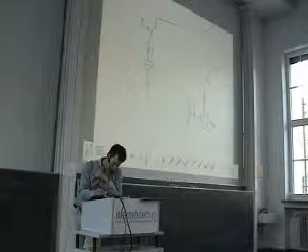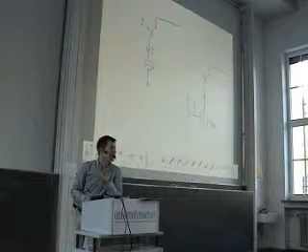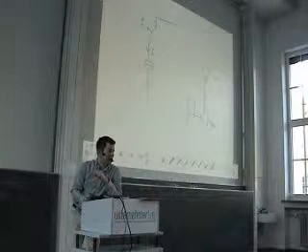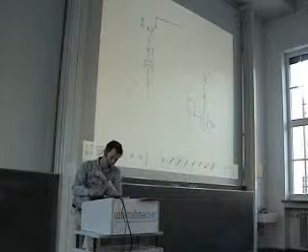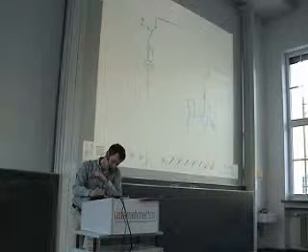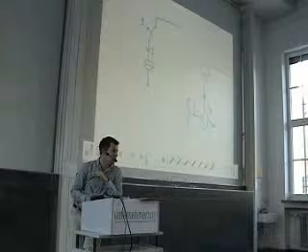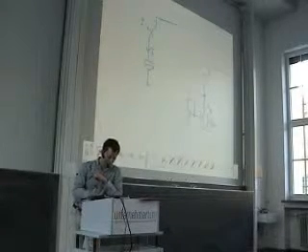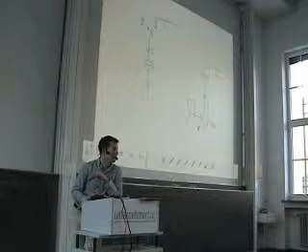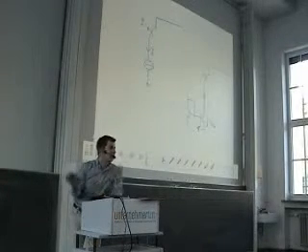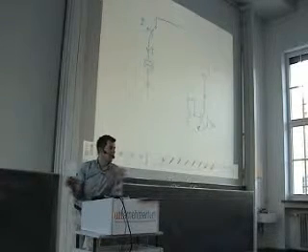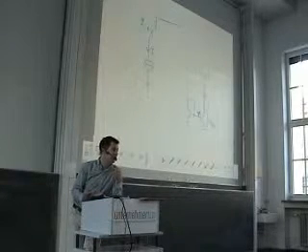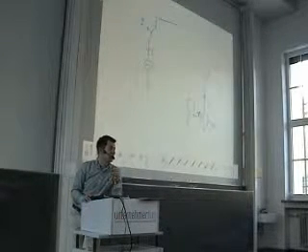If I toggle the switch and switch it to nothing, then there is no current that can flow. So the current source still wants to sink this current, so it cannot sink the current anymore, and hence the voltage here drops down. The voltage drops down until the drain source voltage of this device here is 0. And then the current stops flowing. Of course, then it is not a current source anymore, because the requirement that this device has to be in saturation is not fulfilled anymore.